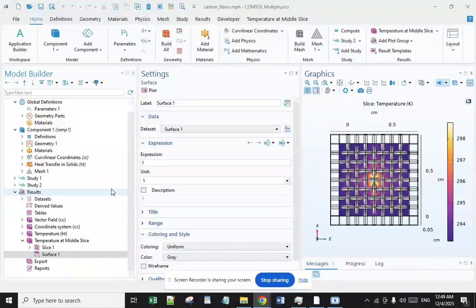The next topic is measurement of the thermal conductivity. The thermal diffusivity was determined from the analysis of temperature map videos captured using a FLIR R300 thermal imaging camera with a high magnification lens, 25 micrometer resolution. And here in this simulation, the two setups for the measurement of the transverse through-thickness and longitudinal one of the in-plane directions thermal diffusivity.